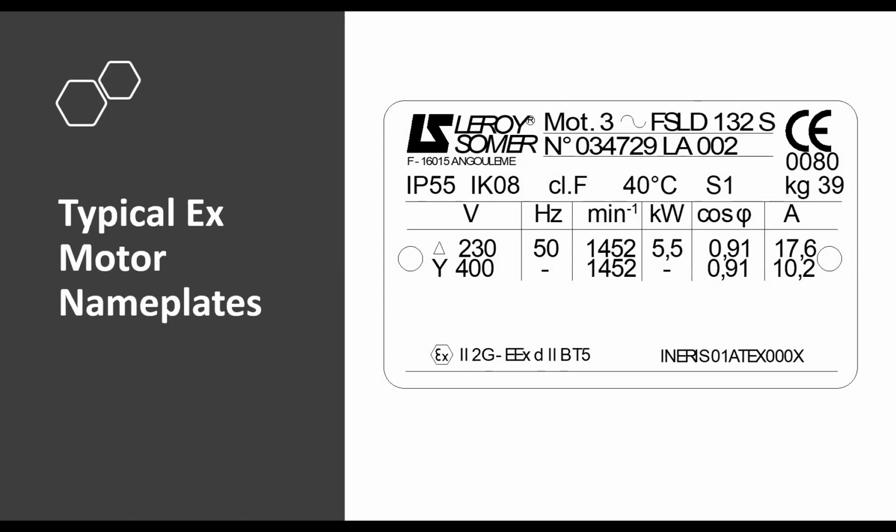And we have another EXD. Again, information string across the bottom, T5, which is 100 degrees. Type of gas, B. Surface industry B type gases. And it's for gas. It's category 2 equipment. You notice there's no EPL because this was certified in 2001.